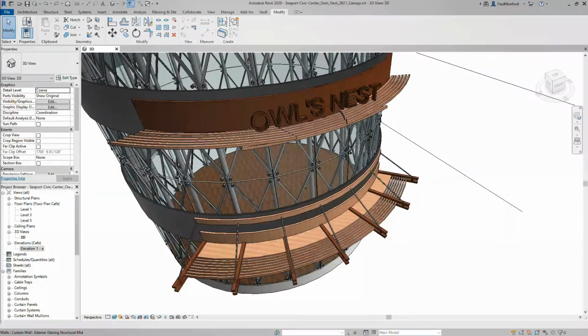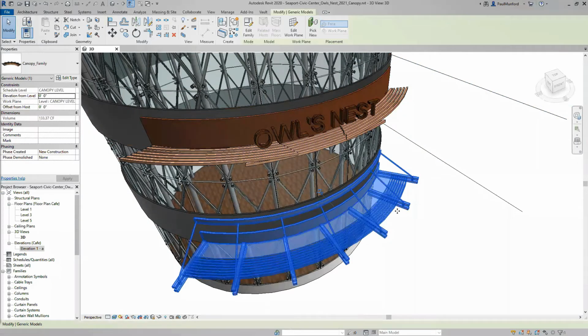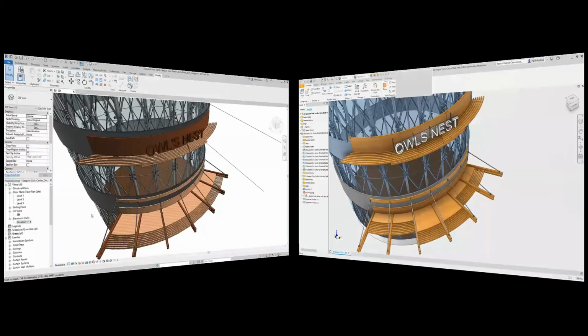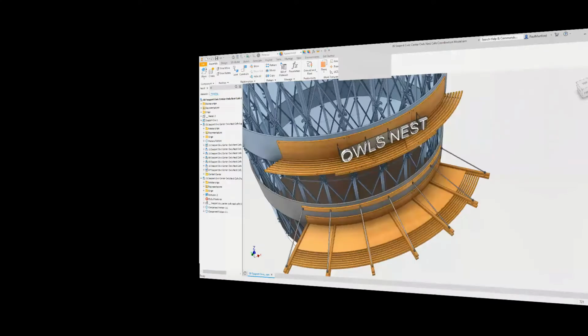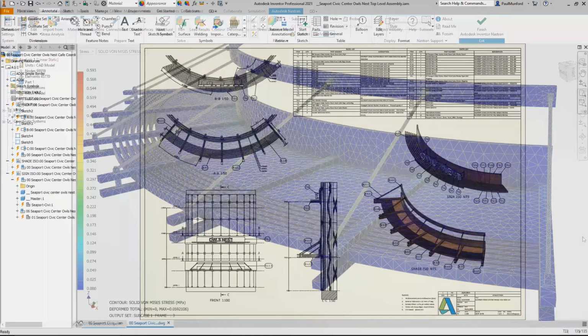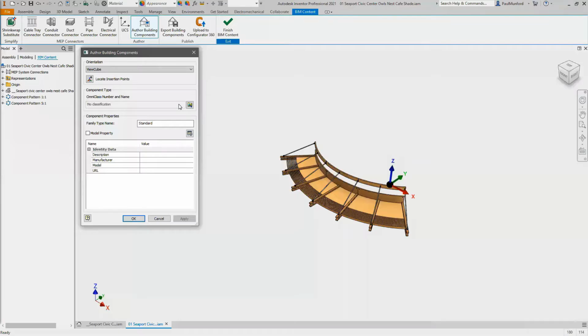Changes during the design process are inevitable, as I mentioned, we all know that. When the Revit model changes, we need to update the Inventor model to suit. Because that Revit model is referenced into your Inventor assembly without file translation, any changes to the Revit project will also update inside the Inventor assembly. A change to a design in Inventor is a change everywhere your design has been referenced, automatically updating all downstream uses of your design model, helping you to coordinate your work to keep up with the change.